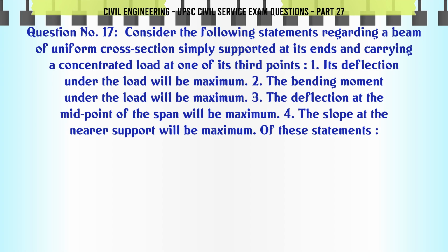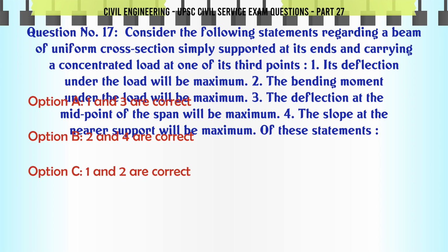Consider the following statements regarding a beam of uniform cross-section simply supported at its ends and carrying a concentrated load at one of its third points. 1. Its deflection under the load will be maximum. 2. The bending moment under the load will be maximum. 3. The deflection at the midpoint of the span will be maximum. 4. The slope at the nearest support will be maximum.